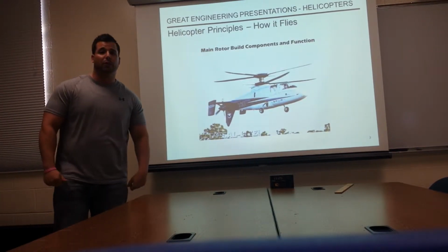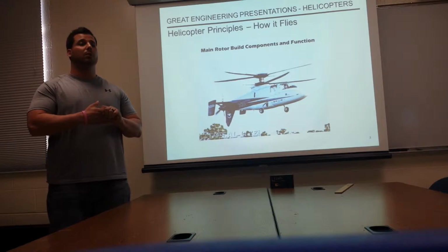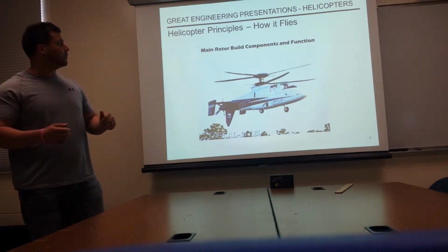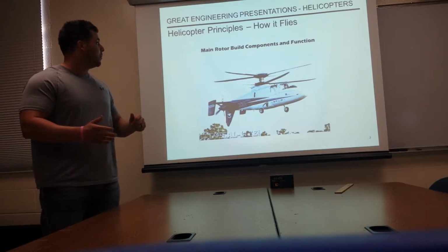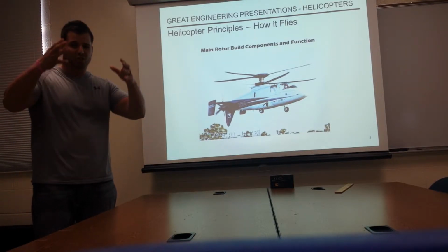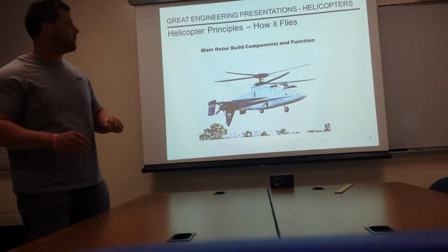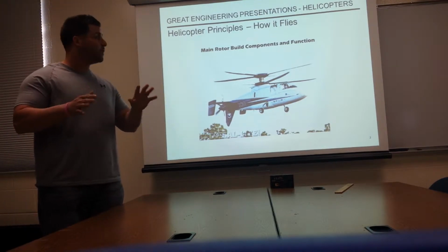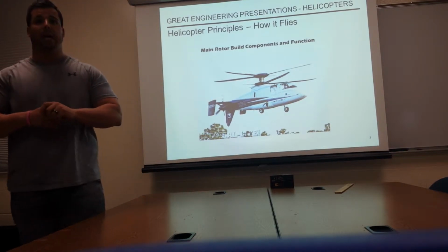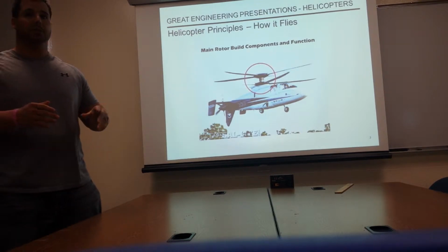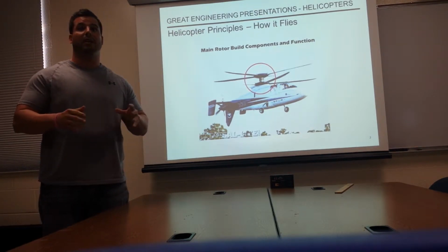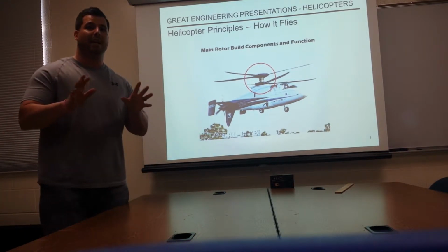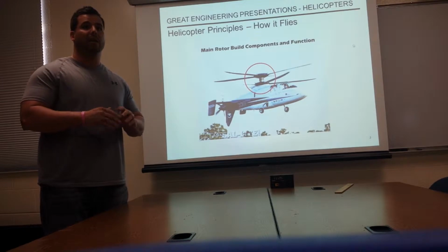Just to go over a few basic principles of helicopters and how it flies. We're going to focus on the main rotor, which is essentially the core of the aircraft. The main rotor is the combination of the rotary wing and a control system that generates the aerodynamic lift force that supports the weight of the helicopter and the thrust that counteracts the aerodynamic drag in forward flight.